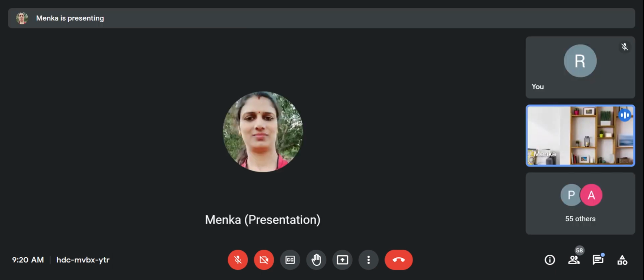Rx is the remainder polynomial. That Rx polynomial will get stored in your LFSR only. So using these two, your signature is compiled. The signature of that particular input pattern is compiled. So what is the input pattern? The input pattern is represented by Gx, because this has the set of sequential inputs. So the input pattern is given by Gx over here.